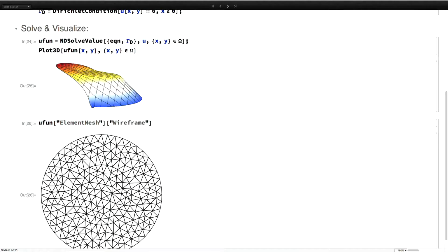Okay, and that internal boundary represents that interface between those two materials. And so it picks up that internal boundary from the governing equations, puts that in there so that the interface is properly resolved. Okay, so that kind of parsing happens inside of NDSolve, and specifically within the FEM framework.